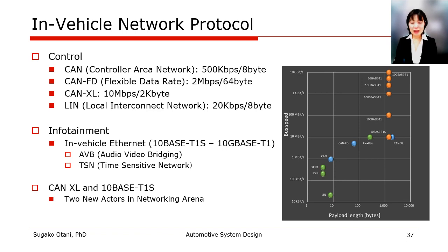Another advancement in Ethernet technology that has expanded its use in automotive environments is the development of the full duplex physical layer technology consisting of a single twisted pair. This robust physical layer started with support for 100 Mbps and meets demanding automotive requirements. Today, transmission speeds are supported up to 10 Gbps.